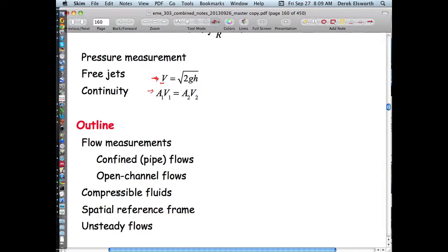Measurement of velocities is much more difficult with, say, a spinning impeller you could use. It used to be, when you pumped gas, you'd be able to see coming out the tube at the side of the gas pump, there'd be a little circular paddle. And the circular paddle would have a pivot through it. If you think of a paddle that would rotate around a pivot and one at 90 degrees to that attached to the same thing, this would actually flow around as you metered gas out of the system to be able to measure the volume that you'd get. Because obviously, if you're paying for gas, you might like to get the correct volume as you pay for it.